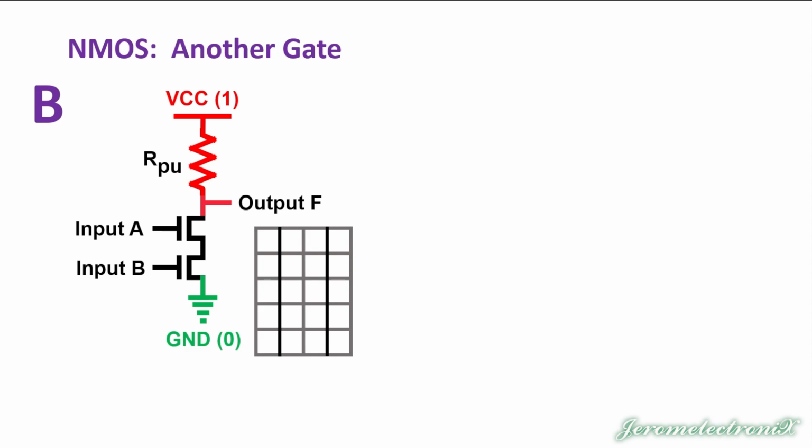When you see these transistors in series, then you realize that what you have is something from the AND family. It could be an AND or it could be a NAND. But if they're in series and something has to go through one and the other, what you have is a variety, don't know yet which kind, but a variety of an AND gate.